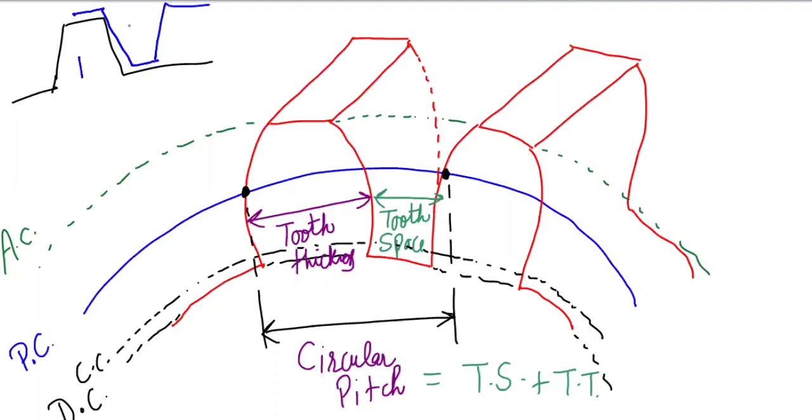Okay, for this gear teeth and this gear teeth, there should be a clearance between the tooth tip and the root of the other gear. So the circle passing through the tip of these teeth is known as the clearance circle. This vertical distance, this time I am talking about the vertical distance, this distance is known as, Anjali, addendum. Okay, addendum is this distance, and this vertical distance is known as dedendum. D-E-double-D. I am writing in short form, addendum and dedendum.